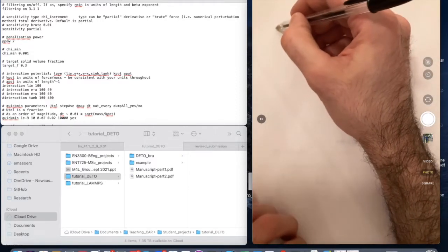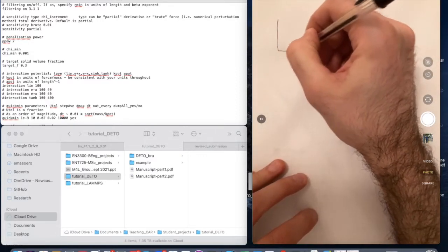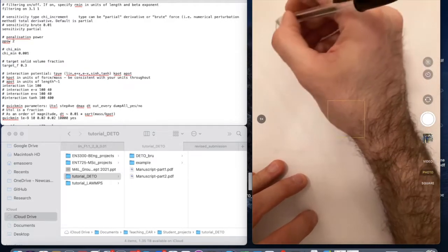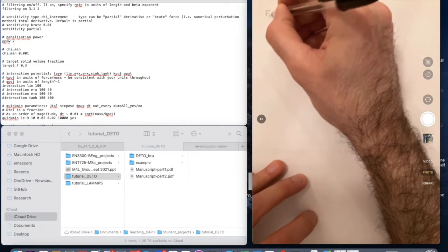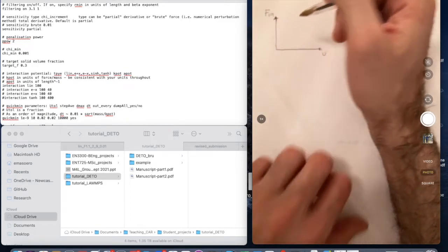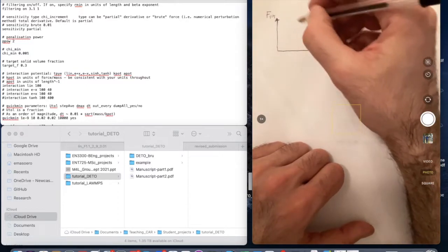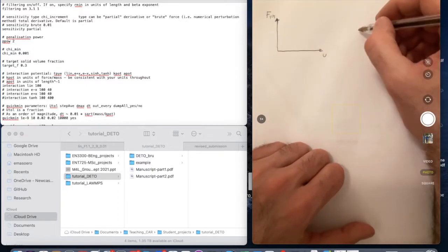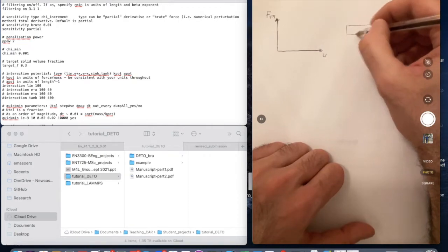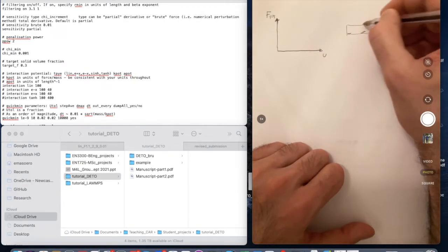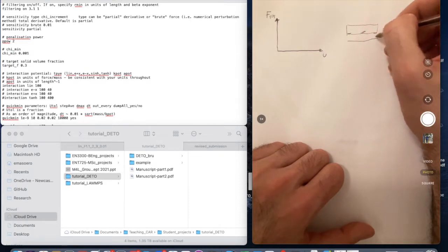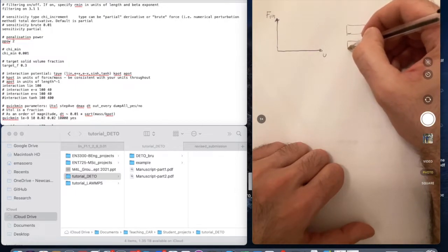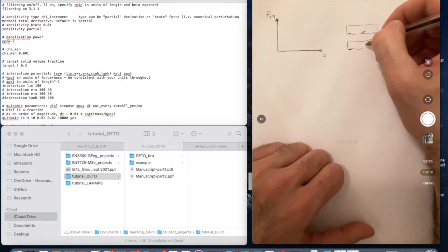So you will plot the total imposed displacement U as a function of the total vertical force of the top particles, the particles that you are moving. As you run a simulation, you start with the undeformed structure and the 3 supports, then you progressively increase the displacement at the top a little bit, and as a result of this incremental displacement, the 3 supports will stay supported, of course, and the rest will deflect.